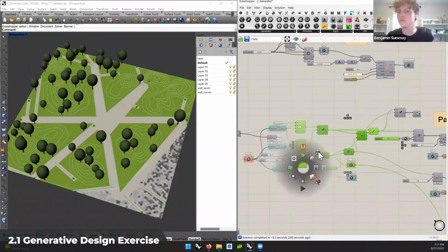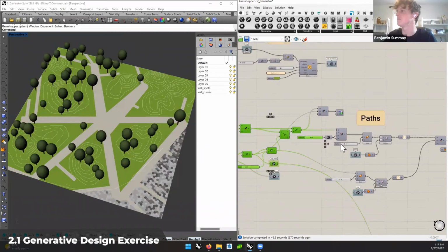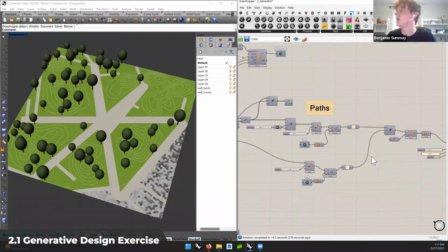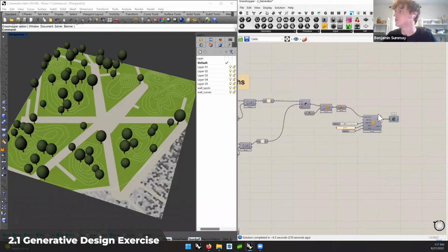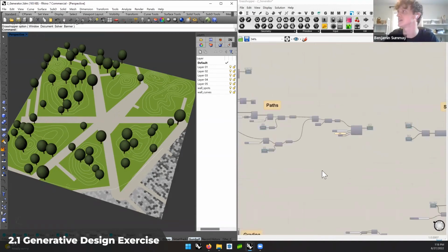And again, I'll try not to get too in the weeds with this, since we want to get through this in a timely manner and talk about the other script as well, given the time frame. But the paths feed back into this whole idea of incorporating Topo Kit into the overall idea, and using the areas and the projecting of areas to create the final product of the actual coloration of the paths. Instead of creating a Brep, coloring the Brep, and previewing the Brep, we're processing everything and then creating a mesh out of that, and then coloring the mesh, as opposed to dealing with lots of different surfaces in the final processing.